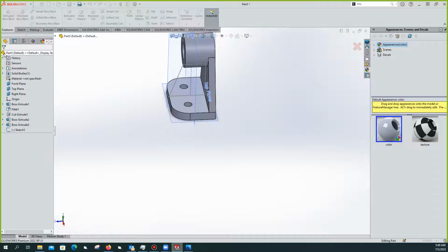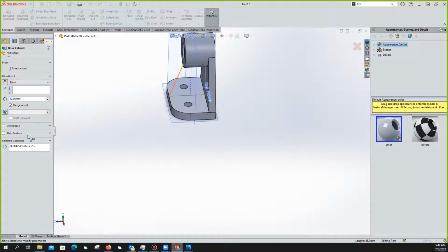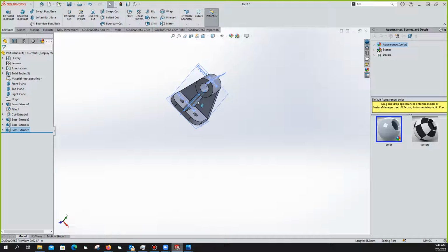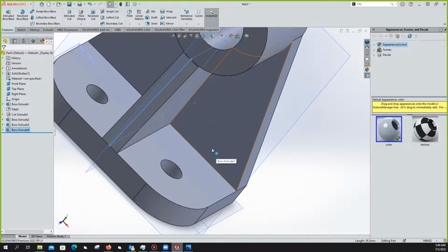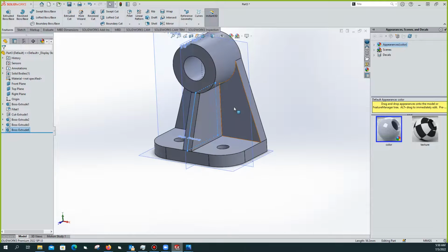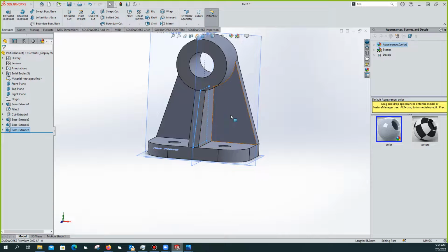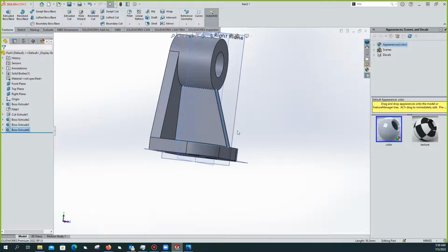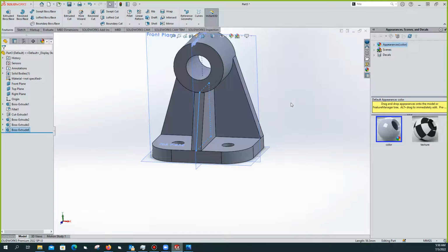Okay. All right. Let me try to say mid plane. So there we go. So in most cases that error comes when any of the lines is suspended in space, when it's not reaching the body of the drawing that you are trying to draw.